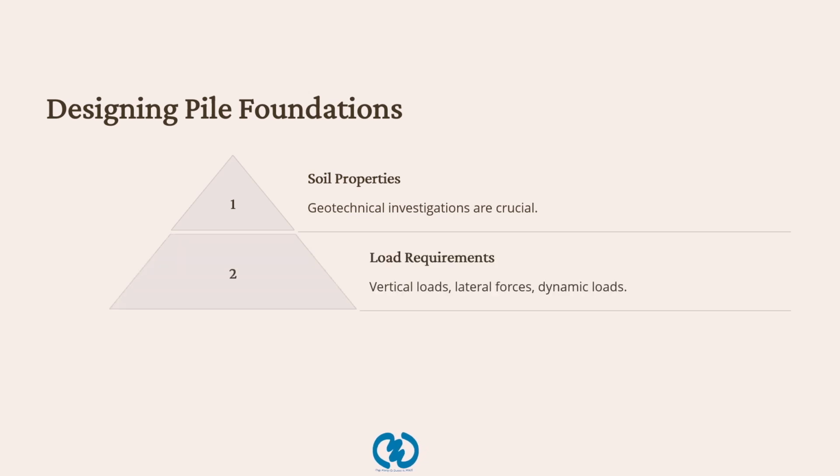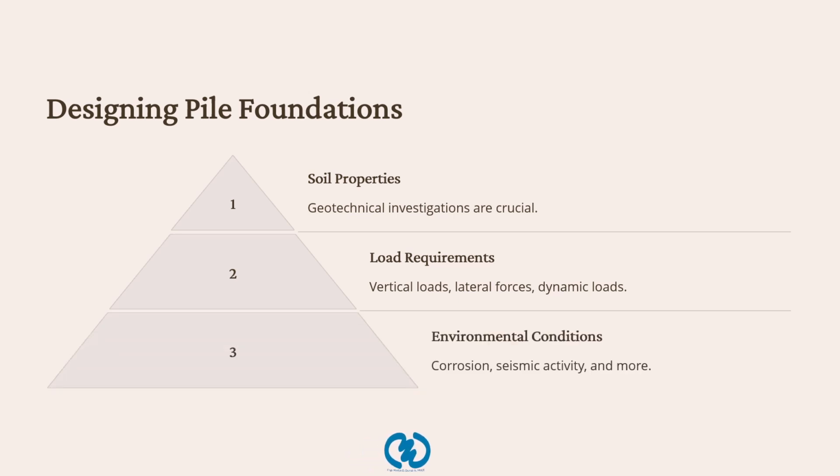Another important aspect is the load requirements of the structure. Pile foundations must be designed to handle vertical loads, lateral forces, and, in some cases, dynamic loads such as vibrations from machinery or traffic. Environmental conditions also influence design choices. For example, engineers must consider the potential for corrosion in coastal areas, while lateral stability becomes a primary concern in seismic zones. Balancing these factors is essential to creating a practical and reliable design.